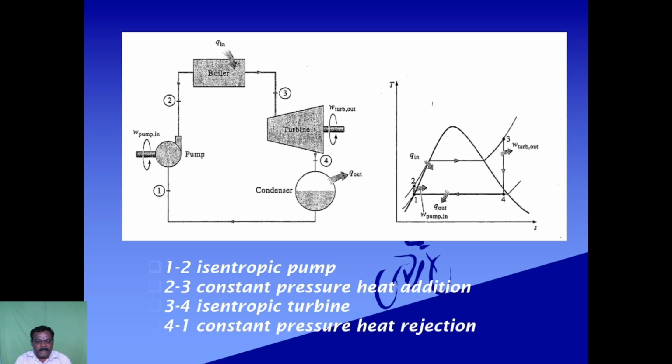Then the remaining things we can't use as they are, but as mechanical engineers, we have to reuse the waste. The waste means low pressure, low temperature heat that comes out from the turbine and enters the condenser. What is a condenser? A condenser is a device to condense the steam. Here the low pressure, low temperature steam is converted into water. So the output of the condenser is only water.